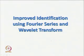In today's lecture, we shall see how one can make use of Fourier series and wavelet transform for obtaining accurate limit cycle parameters. That will give you again accurate critical gain and critical frequency. Those are used in analytical expressions to find the parameters of a transfer function model.